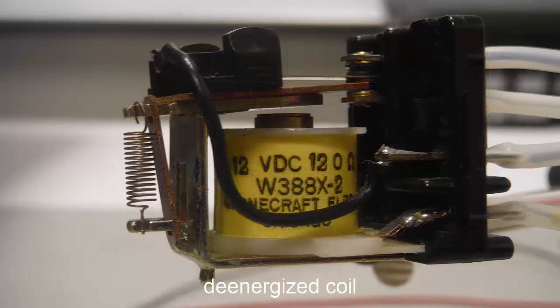One can see the actuation mechanism internal to an IceCube relay. When de-energized, the spring pulls back on the lever and the common in the center is making contact with a normally closed contact at the top and disconnected from the normally open contact at the bottom.